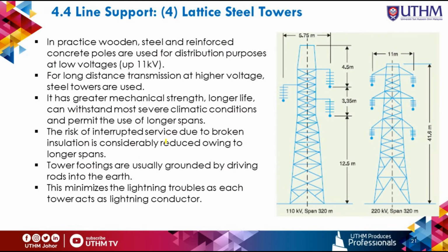And then the fourth line support is the lattice steel towers. In practice, wooden, steel and reinforced concrete poles are used for distribution purposes at low voltage, say up to 11 kV. However, for long distance transmission at higher voltage, steel towers are invariably employed. These steel towers have greater mechanical strength, longer life, can withstand more severe climatic conditions, and permit the use of longer spans.